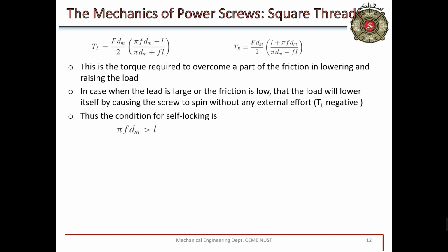For example, self-locking was the main concern for the power screw, because if there is not sufficient self-locking, there is not a sufficient locking mechanism. If you are lifting a car with a power jack and it is not self-locking, then the car will fall down without any application of torque or force.